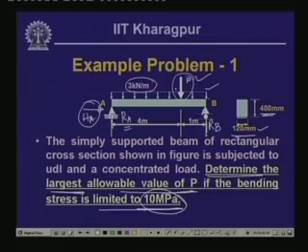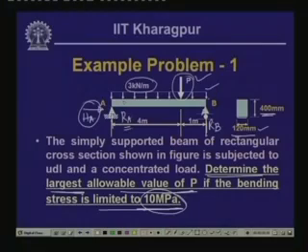Now, if we separate out these two loadings, as you know that we are dealing with the stresses within the elastic limit, hence we can individually calculate the effect of these two different loads and can superpose them, we will get the same effect if we take the combined loading. So, we have seen that for uniformly distributed load the reactive values will be half of the total load, and for the concentrated load we can take in proportion to the distances.